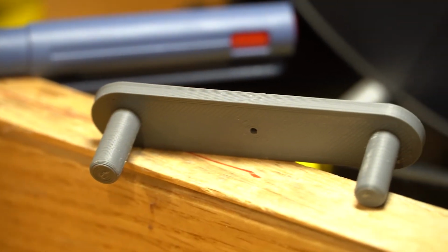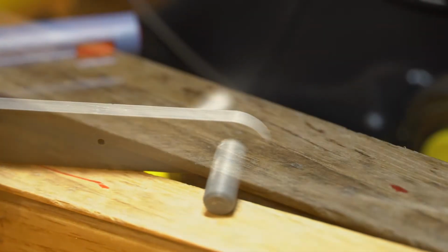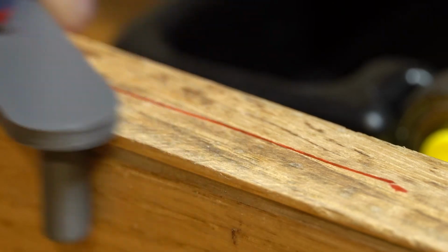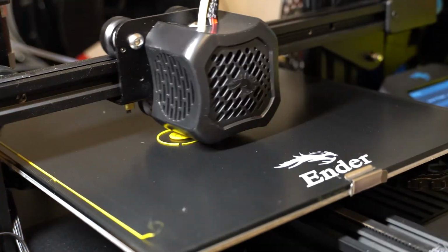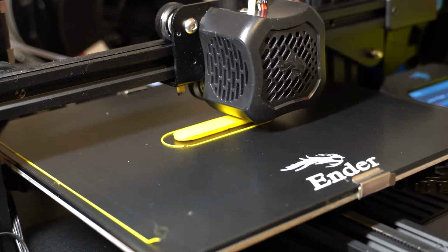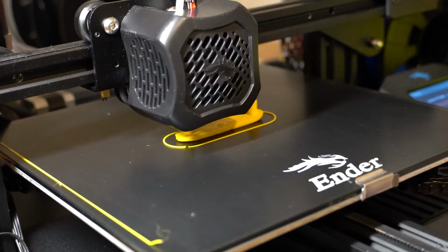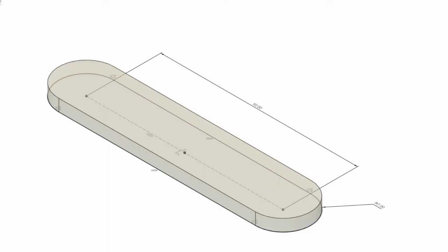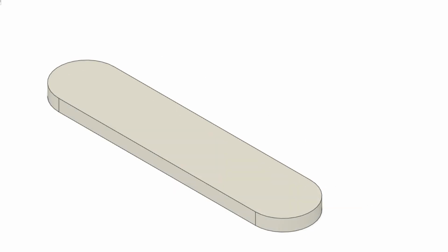Let's look at this being used to model another center finder for woodworking. We can design for the same function that was shown in the 2D video, but this time design for 3D printing. The approach used for solid modeling is to incrementally build the complexity of the design. We model the part by adding features one after another, starting with a base feature. To form the base feature, we design the 2D profile for the main body of the center finder, which we can then extrude to create our first solid feature.